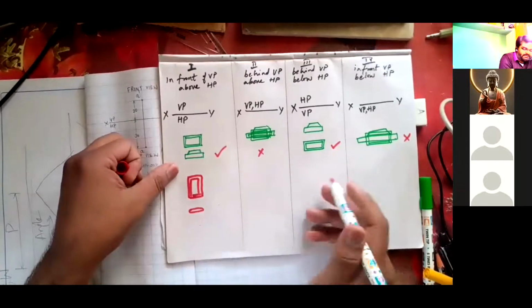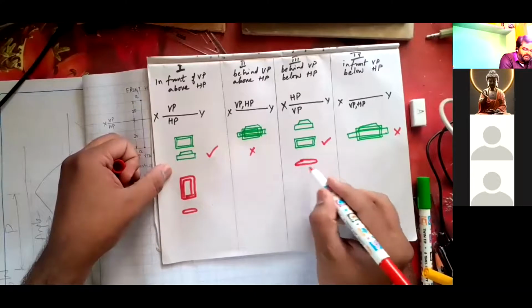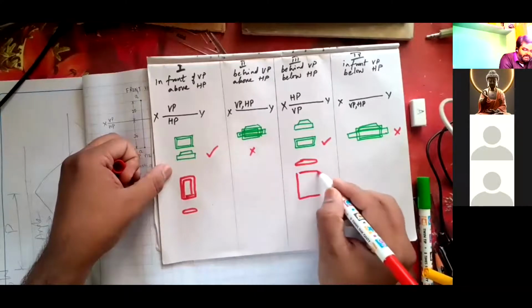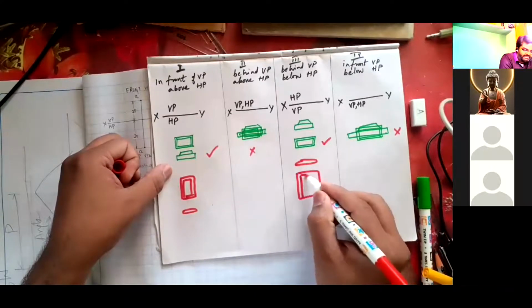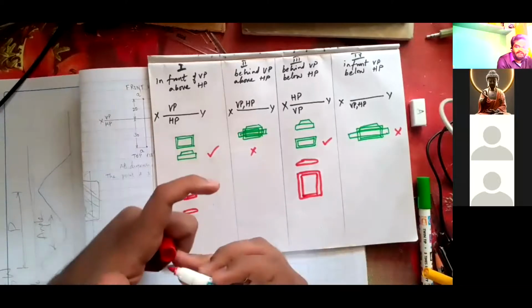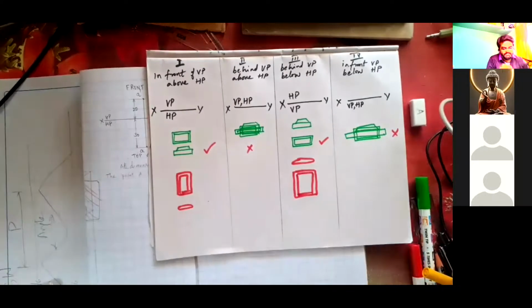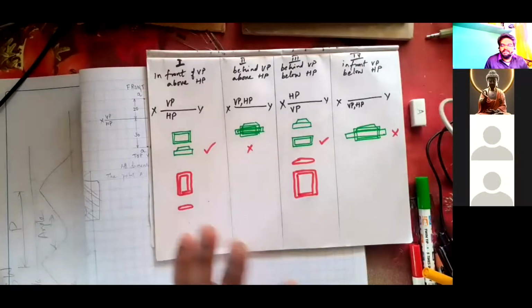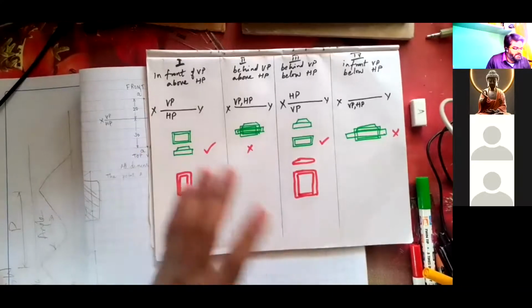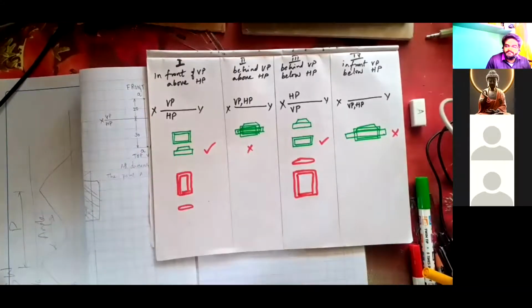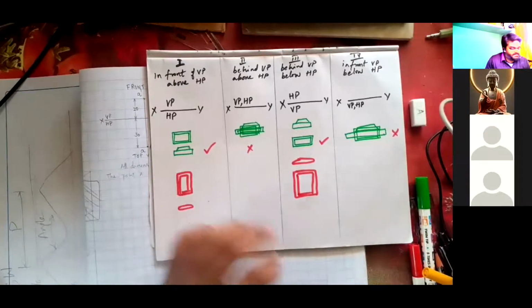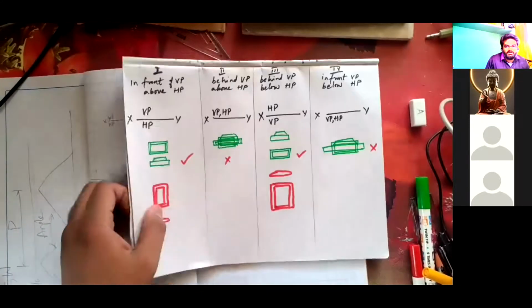In third quadrant, if you keep it, top view will be above and front view will be below. This is the major difference between first quadrant and third quadrant. Don't say that these are not mobile phones; of course, I'm just representing images to make you understand, that's all. Any doubts, please discuss, about all these four quadrants.